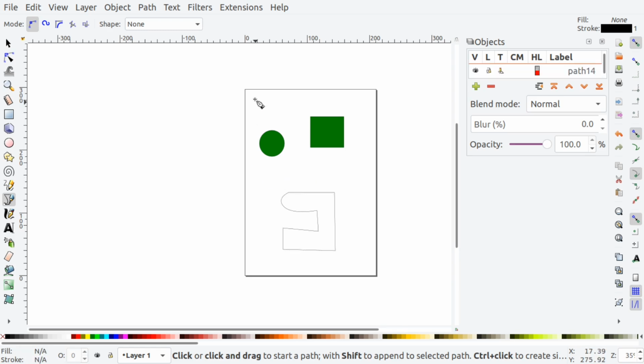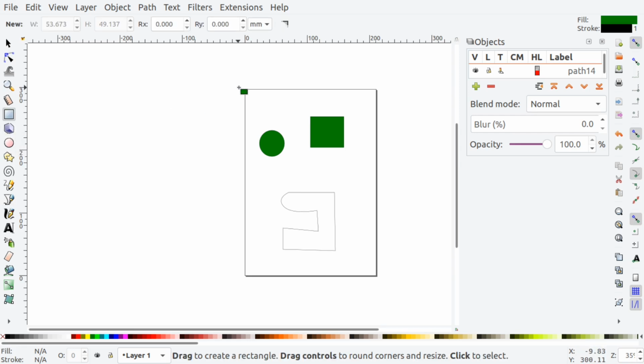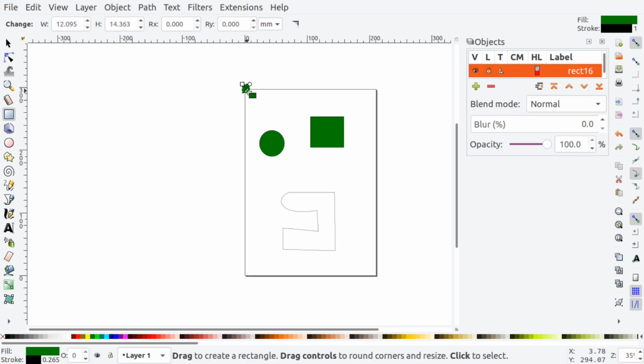Now, one thing to remember is that in this document, the coordinates of x0 and y0 start at this point here. So when we right click and transform these parts, because these individual parts will be paths inside FreeCAD, the handle to transform them will be at this point here. So I'm just going to add a small square, say here, and we'll see that it is at that point.